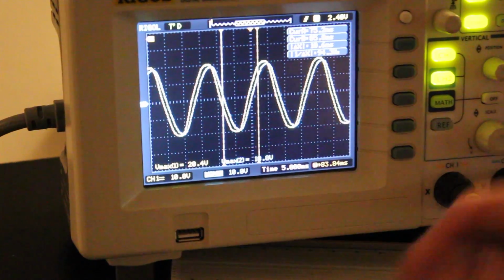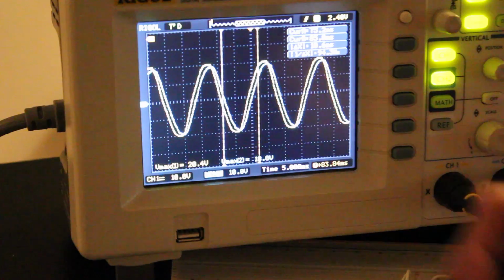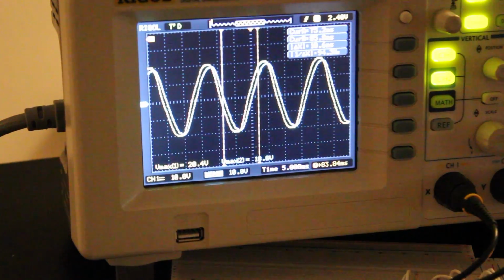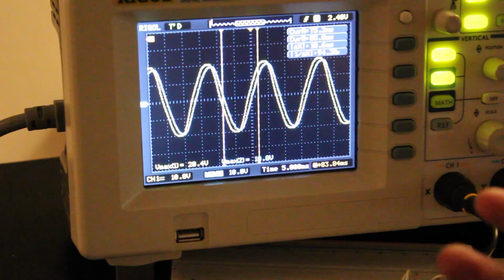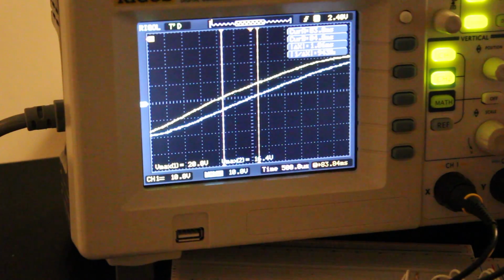Now, I explained this before. The entire waveform is 360 degrees, and it's delayed by 20 degrees. So we know 360 degrees of a 60 hertz signal is about 16 milliseconds. To convert the 20 degrees into time, we can simply take 20 times the 16 milliseconds divided by 360. And we'll be left with about, not 3.5, 0.9 milliseconds.